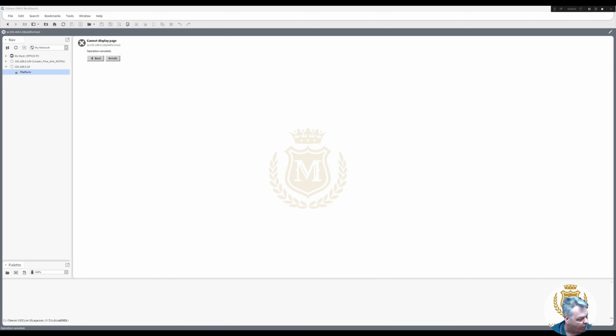Today we're going to program from the beginning, including commissioning an Edge 10 controller, Niagara Edge 10. Now it has DHCP. I've put it on my network and it's automatically given it an address of 192.168.0.18.